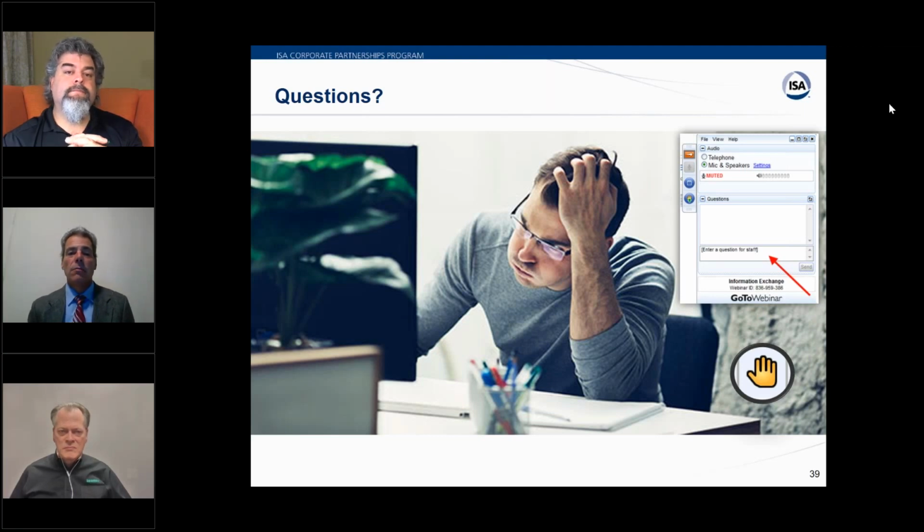There's nothing in any document that says your testing has to be done offline. If you've, again, got a 7-year turnaround, you need to test more often than 7 years. So it's perfectly acceptable and common to build in capabilities for online testing, whether it's bypasses around a sensor or bypass valves around a valve. It just depends on the calculations that I was showing earlier. You can determine what your test interval needs to be. And if you can't do that, or you need to do it more often than every turnaround, then you need to build in online testing capabilities.